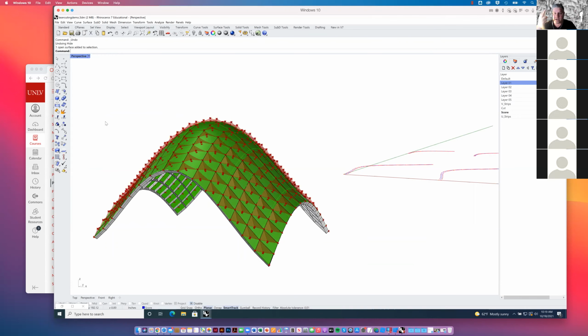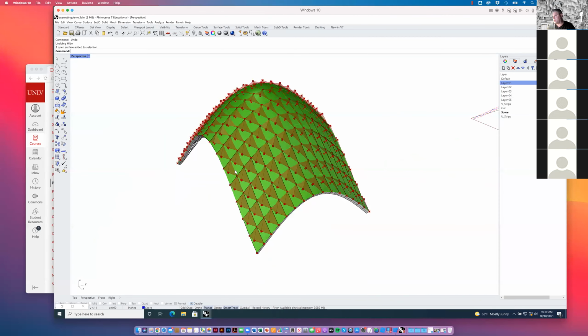You can also begin to talk about prefabrication in a factory facility, and so it begins to add precision to the equation. The fewer things you have to do with a tape measure out in the middle of the field, in a dusty pit of a construction site, the better. Because it's a lot harder to make things line up when you're 30 stories high and it's blowing wind and rain and sleet and snow. So the more of this that can be resolved offsite, oftentimes the more economical these systems can be. So there's a value proposition to this.